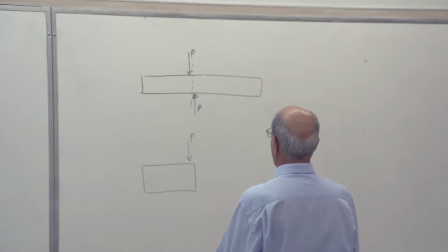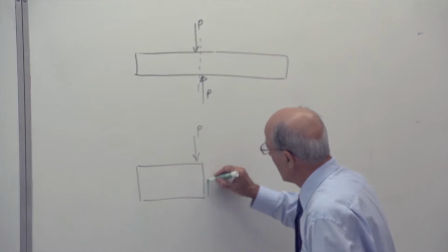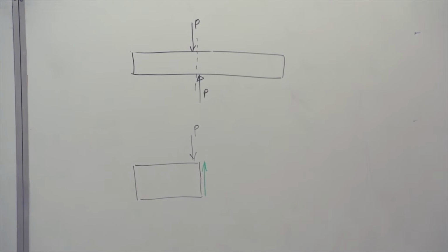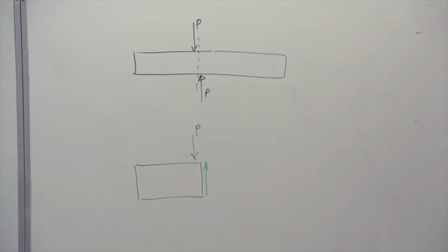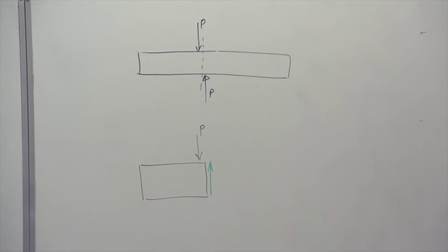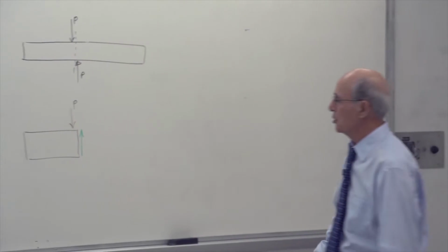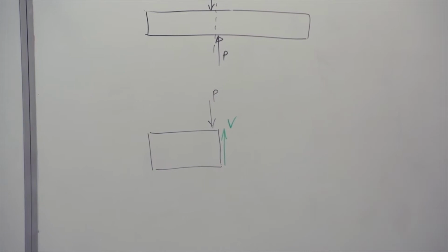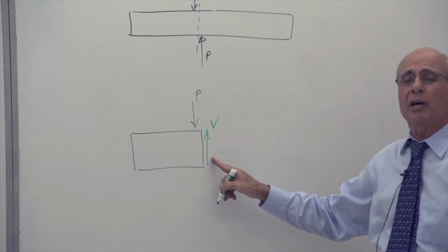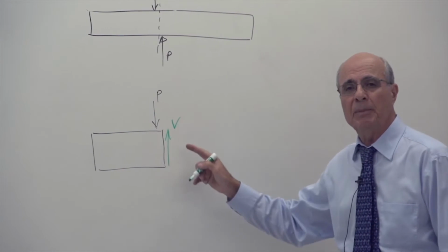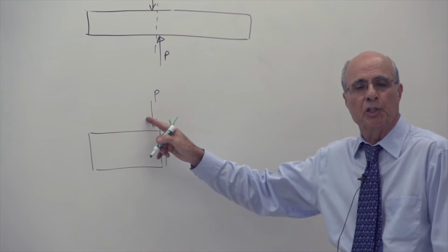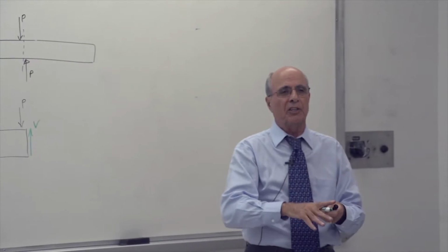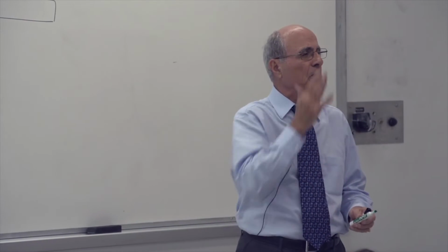Now, statics tell me again, like before, I should have here a force in the section, yes or no? That force in the section is not normal to the section. It is in the section, then we call it shear force. Remember that? We talked about it last time. So let's call it, is that correct or not? Yeah. Again, statics tell me these two are equal. Again, this is imaginary. There is no shear here equal to that. What is inside the body, because you are trying to cut the body, is a uniformly distributed stress there, yes or no?